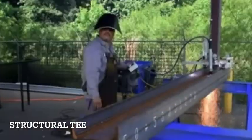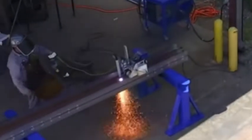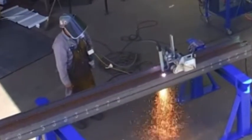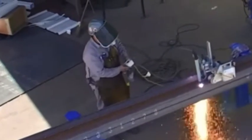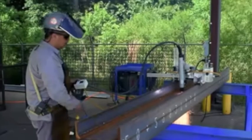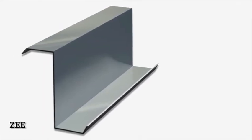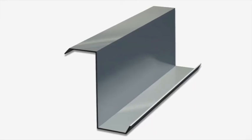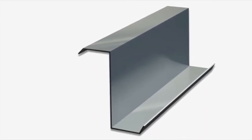Number 3. Structural T. A structural T is a structural steel section cut from a W, S, or M shape and having a T shape. It is designated by the prefix WT, ST, or MT, depending on the section from which it is cut, followed by the size and weight of the member. A rolled metal bar having a T-shaped cross-section is also called a T-bar. Number 4. Z. It is a rolled metal bar having a Z-shaped cross-section with internal right angles. It is also called a Z-bar.